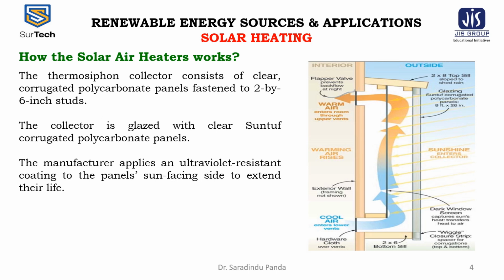This type of glazing, which consists of two sheets of polycarbonate separated by the supports waves, also simplifies the installation since it requires less support and does not have the corrugated edge that requires the sealing. Buildings in cold climates will benefit the most from this change, which would increase the cost by around $100.